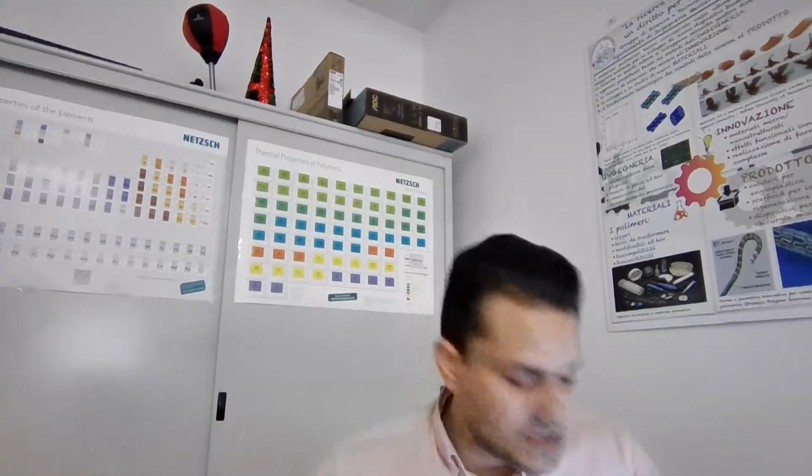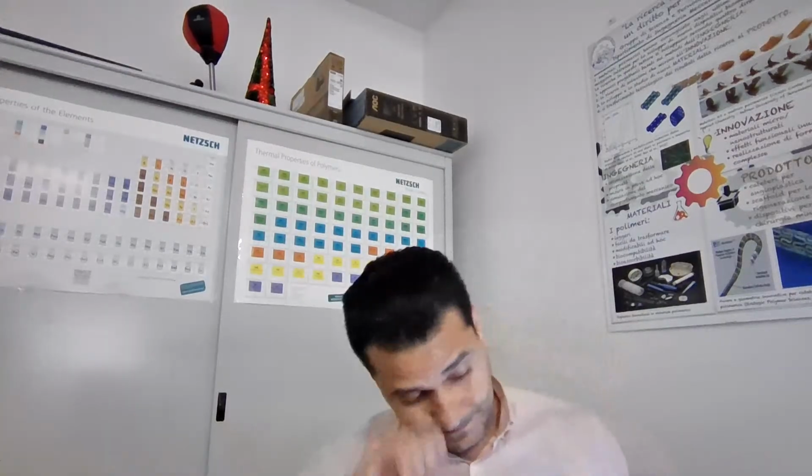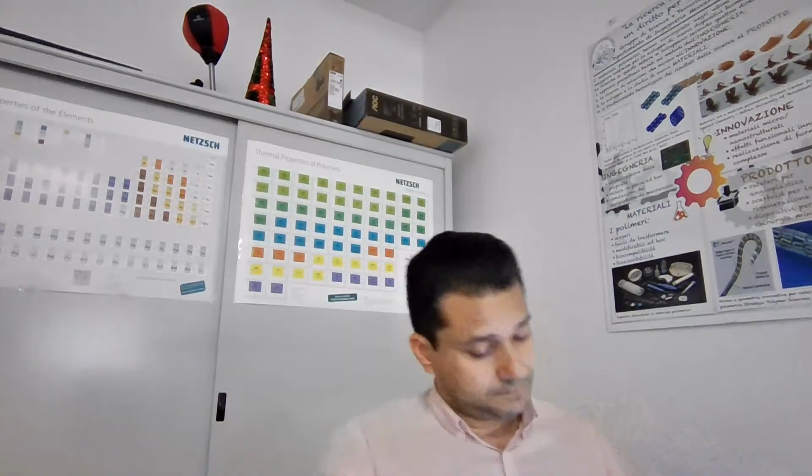When I build a wave vector related to this, I won't use L. I use 2π divided by D, where D is the diameter of those particles. So when the tire surface is covered by hard particles of linear size D, the rubber will not be able to penetrate fully into the road asperities.